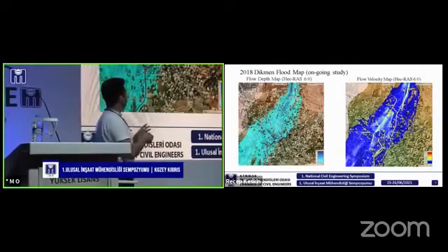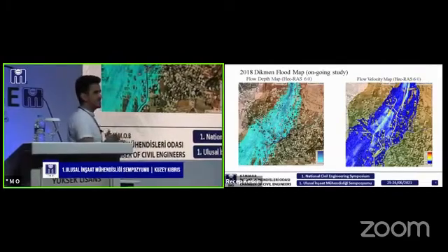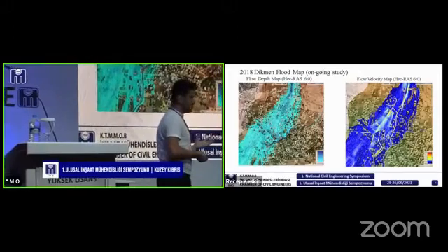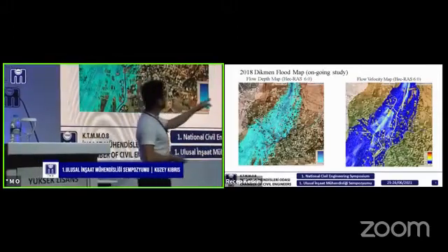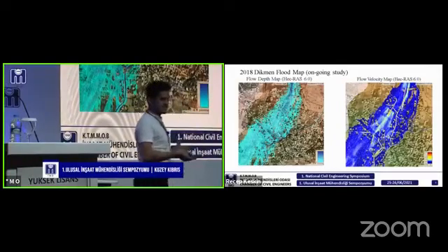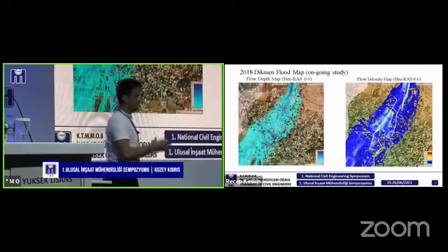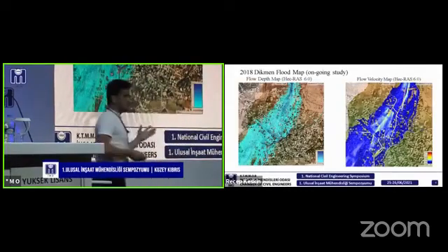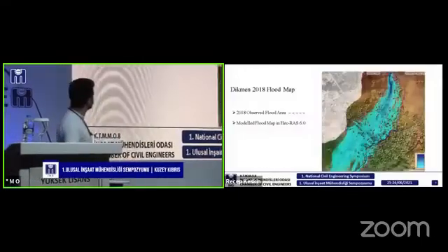We didn't consider the influence of the floods from the city, since it's an ongoing study and various inputs in different scenarios can influence it. For example, we only consider this as an open channel, but there are some culverts and bridges that are probably filled, or their openings are not as we considered here. So with the inputs of those data, we can improve our models to a better sense.